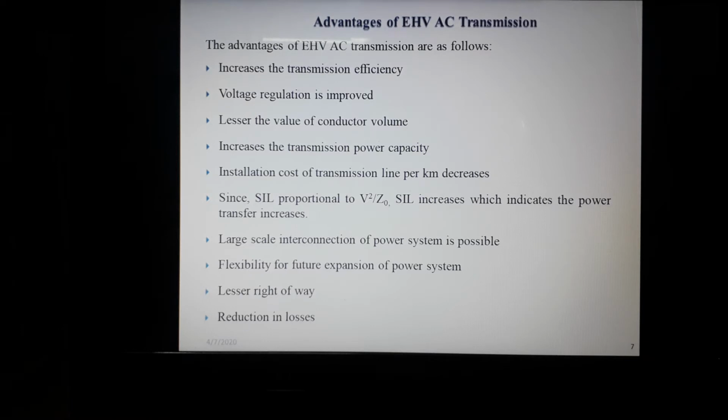The surge impedance loading is proportional to V square by Z0, where Z0 is the surge impedance, given by root L upon C, L being the inductance and C the capacitance of the line. So SIL increases, which indicates the power transfer increases with increasing transmission voltage level. Large scale interconnection of power systems is possible with EHV AC transmission, and it is flexible for future expansion of the power system in case of increasing power demand.